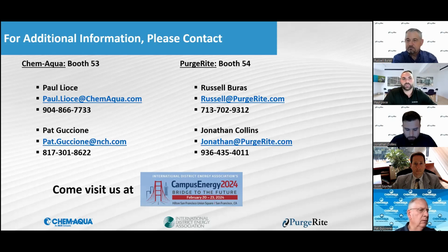Because we would love to see that all go through, because if not, then you're looking at looping each individual air handler. So if not, you'd have a dead leg, so you'd put in temporary pipe, then having to disconnect that, reconnect. And we would love that. But it's ultimately checking with the manufacturers of the equipment and getting the A-OK for it. Yeah, and we prefer to go through everything, ultimately.